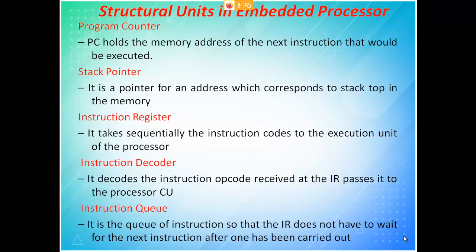So for example, at line number 6000 you have an instruction called call 8000. So what will happen? Initially what is the first step? Opcode fetch. What is the opcode fetch you are doing? Opcode fetch you are doing for the instruction call or jump. Okay, I repeat, let us assume at line number 6000 you have an instruction called call 8000, which means I am going to jump to the line 8000.